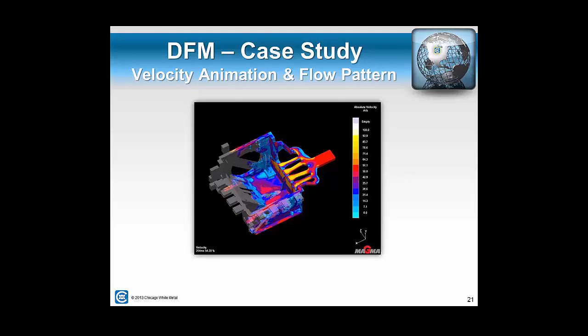In the end, for velocity and for many of the other images we'll look at from the mold flow analysis, you really want it to be in the light blue shade as much as you can. So here you see that the high velocity areas are concentrated into the overflow outside edge rectangular features that are actually trimmed off and not used on the part. So that's what we want. We want those features to have all the air and the other entrapped gases instead of on your part.